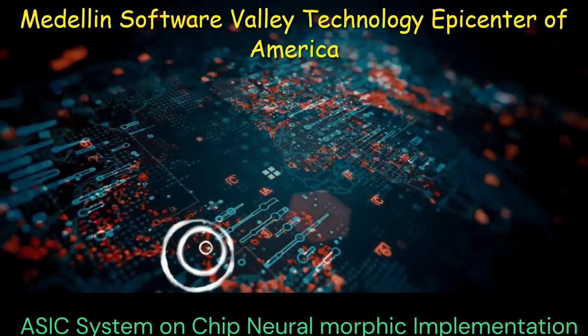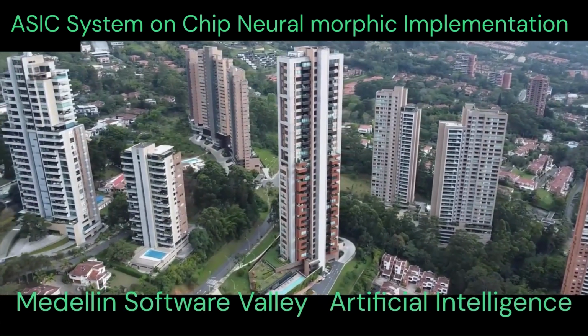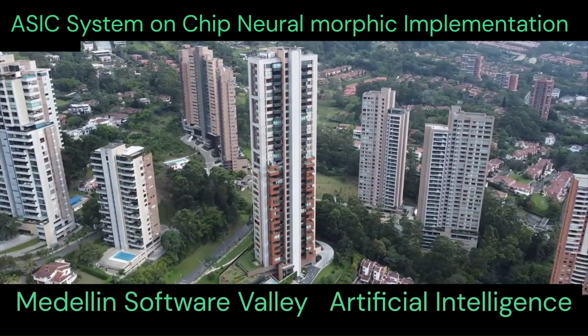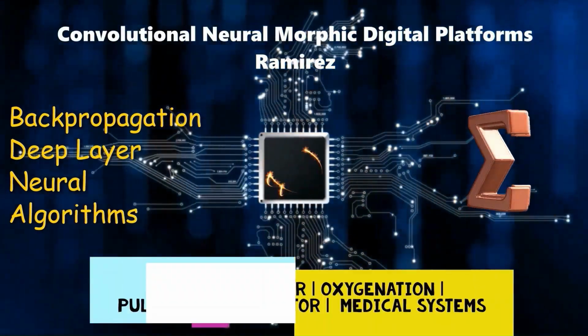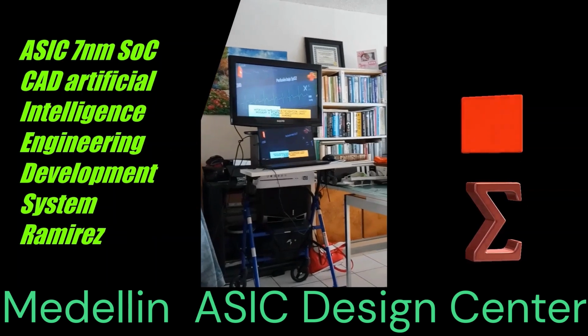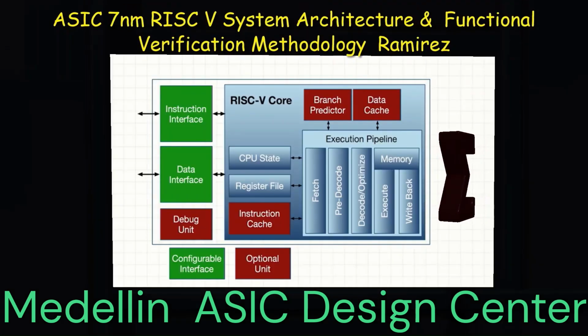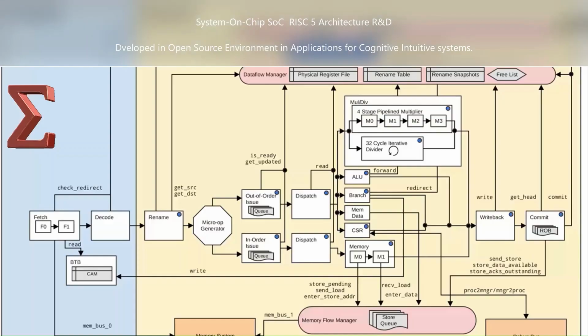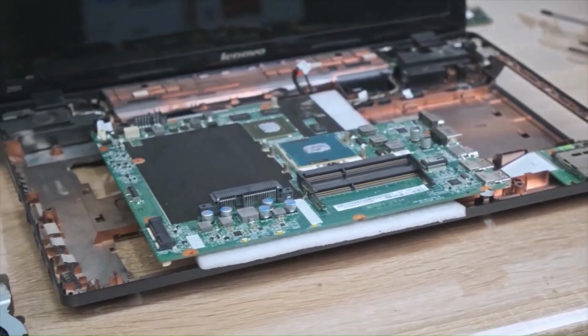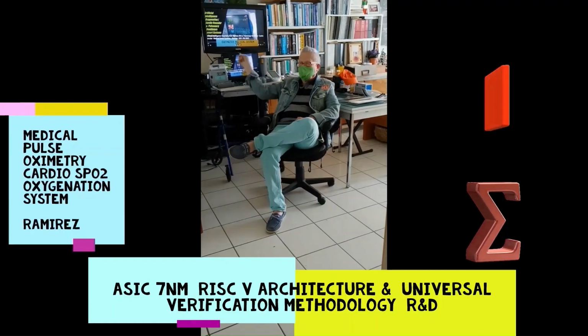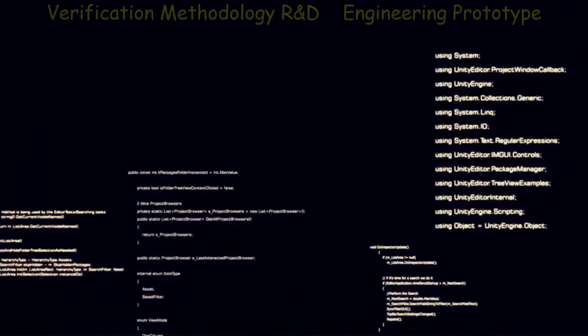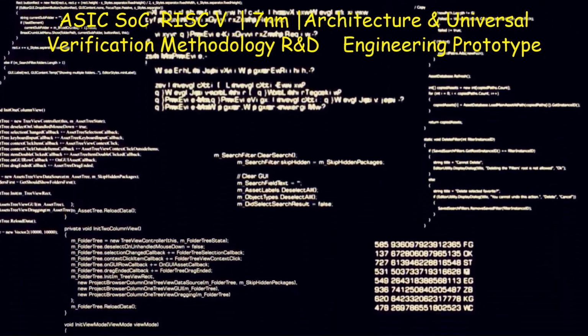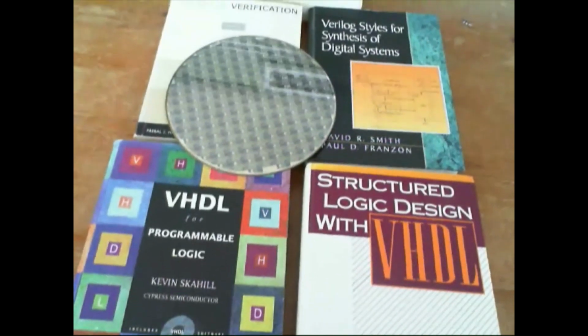The RTL was successfully developed for this ASIC/FPGA system. After functional verification, we also synthesize the unit into a gate-level netlist. Then timing verification was performed to verify that the system on chip multi-core system meets timing requirements. Once the design meets timing goals, the netlist is given to the physical design, which places and routes the design, and then finally the chip is built and tested.